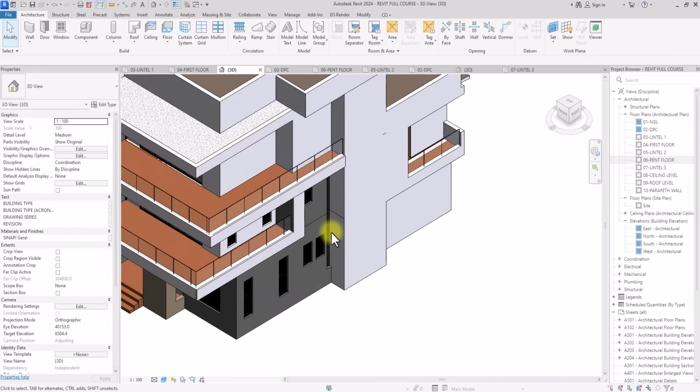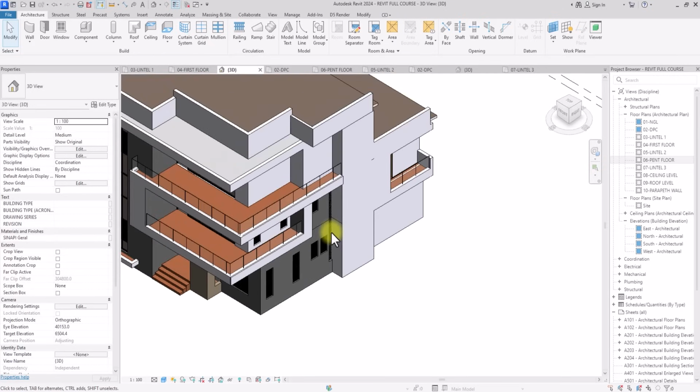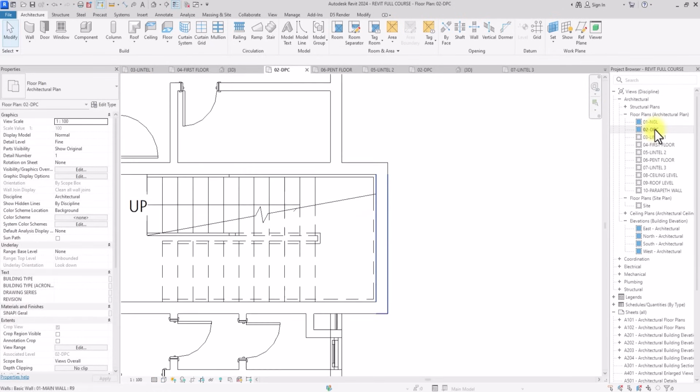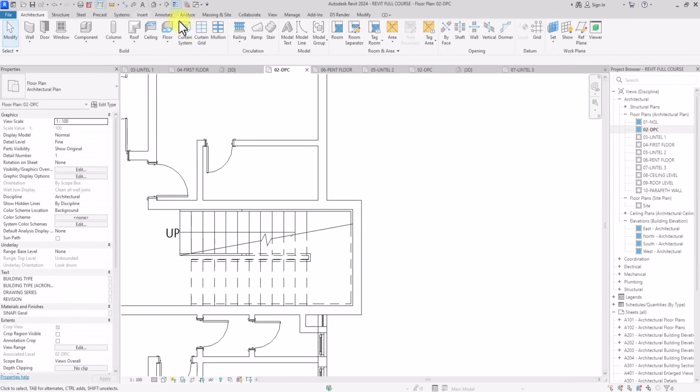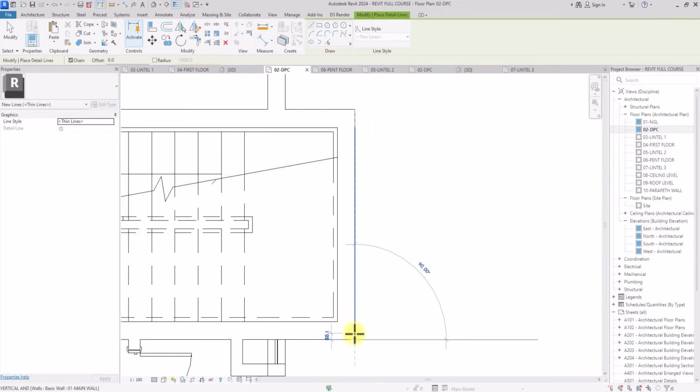All right, now, so before doing this, we are just going to add some fenestrations to this stairway. So we're going to go to DPC again, and we're going to start drawing long, narrow fenestrations in the stairway area. So I'm going to just use detail line to offset 600 from here, for the sake of facade character. And I'm also going to do this and offset 600 from here.